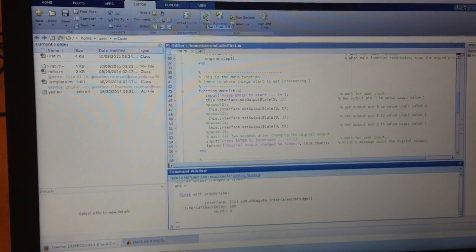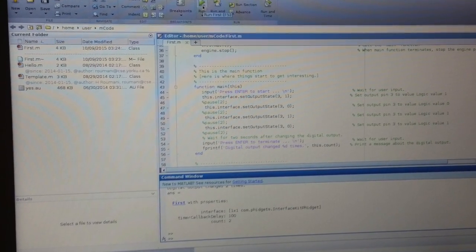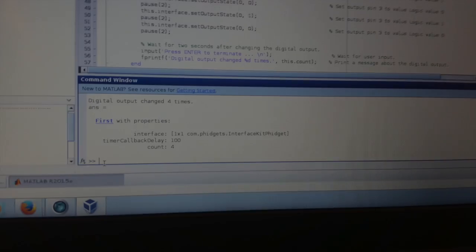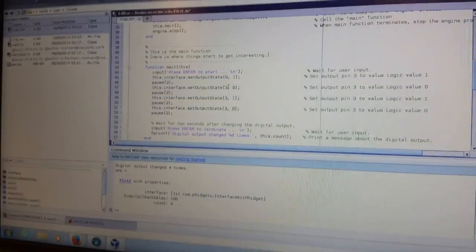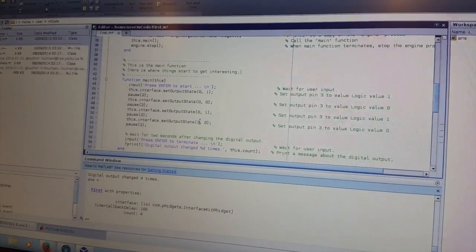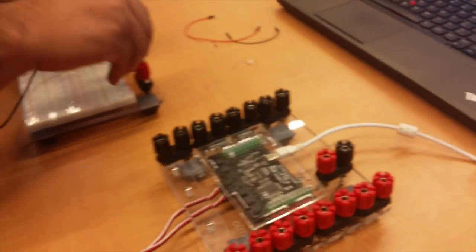This is step 19, in which we repeated the previous steps 2 times, giving us 4 overall inputs, which changed the value of the count to 4. This is step 20, in which we began to build a circuit on the prototyping board using a resistor and an LED light connected in series between the digital output 0 and the ground terminal of the interface board.